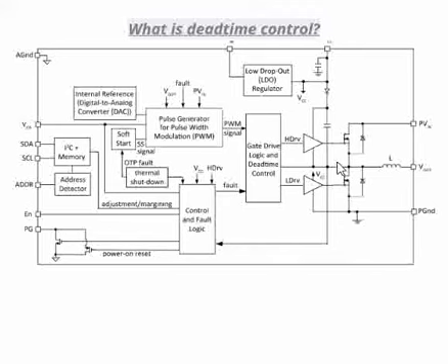So imagine a scenario where you have the high side MOSFET turned on and the low side MOSFET also turned on. So there is a direct shot from this node to the ground, and this node is nothing but the power input to the MOSFET.